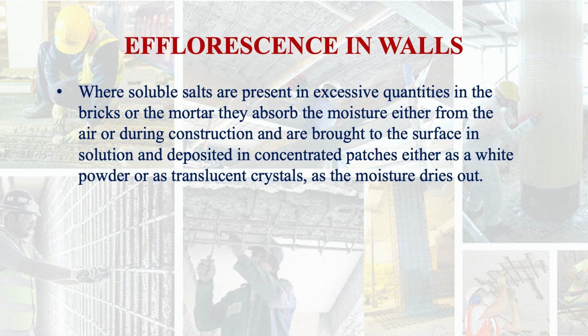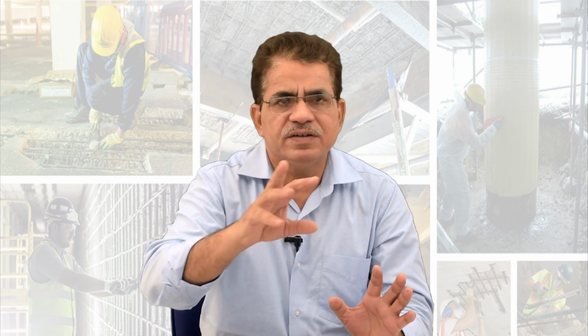Efflorescence in the walls. Where soluble salts are present in excessive quantities in the bricks or the mortar, they absorb moisture either from the air or during construction, and are brought to the surface in solution and deposited in concentrated patches, either as a white powder or as translucent crystals as the moisture dries out. After drying of the moisture, you will see either the white powder or the translucent crystals.